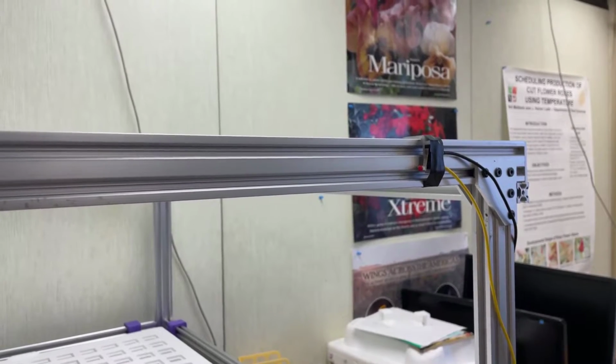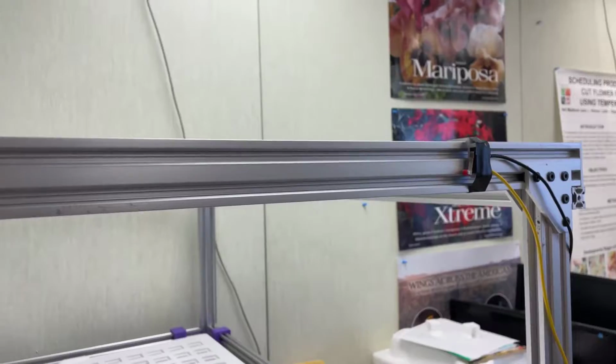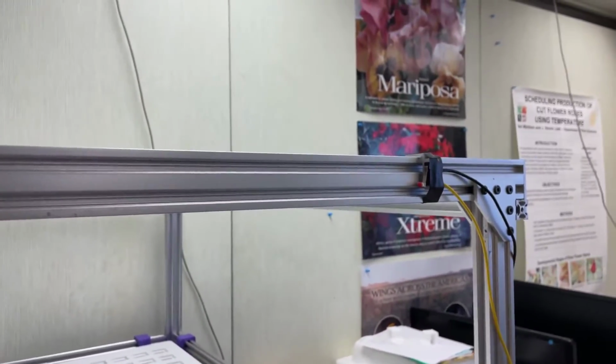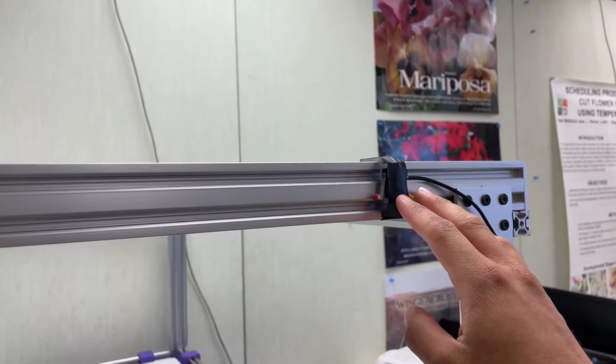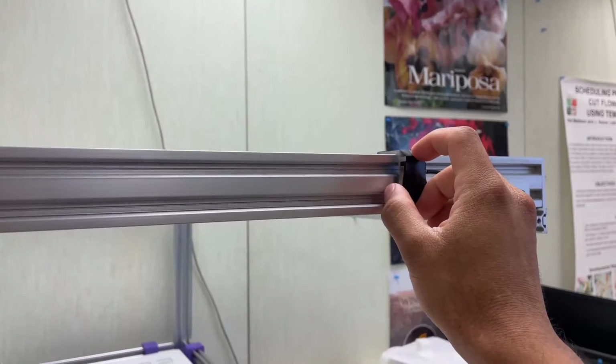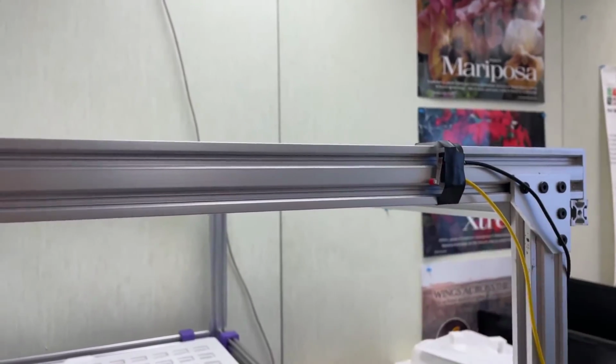Occasionally, during operation of the frame, the tool head may begin to move unexpectedly. When that happens, you want to check on these limit switches at the corners of the frame. Make sure they're secured, they're not going to move. Make sure that these switches click nicely when pressed.